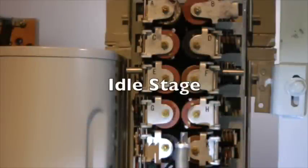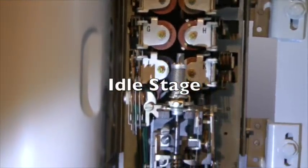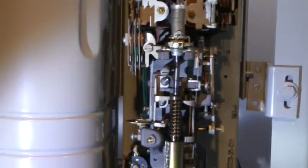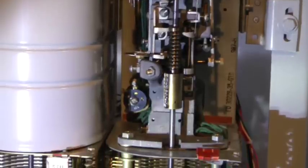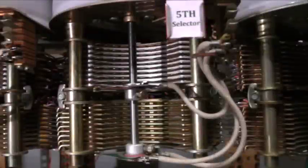Now we are going to begin a detailed look at all the stages of the operation of the connector. The first stage is the idle stage. No relays are operated, and the shaft and wipers are in their normal rotary and vertical rest positions. We are going to follow the progress through the connector of a call through my demonstration unit to Pennsylvania 6-5000. We will begin at the immediately preceding 5th selector. This selector will process the dialing of the hundredths digit of the called station, which is a 0.